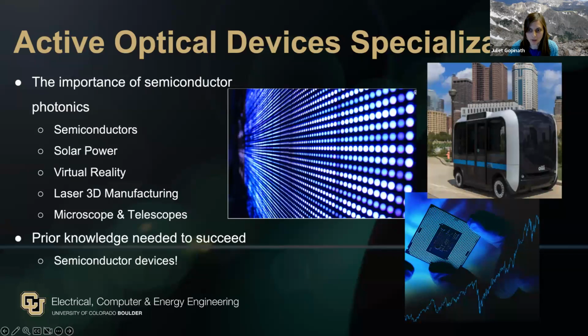Another area that's generating a lot of interest is 3D laser manufacturing. Lasers can be used to build cars or robots through cutting and welding. They can be used for 3D printing via stereolithography, in which a laser is used to cure a photosensitive resin, thus making a 3D solid. This can be used for everything from toys to models to complex optical parts that are manufactured today. Metal powder bed fusion printers use 500-watt lasers, whereas those used for cutting can be in the kilowatt range.